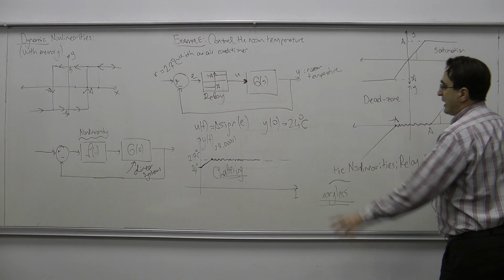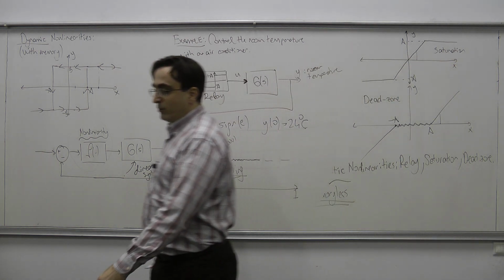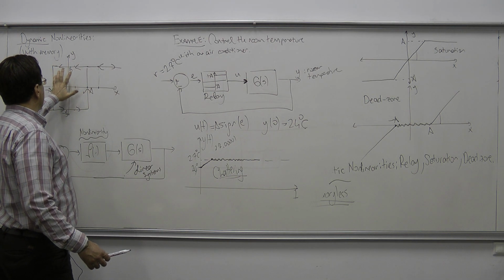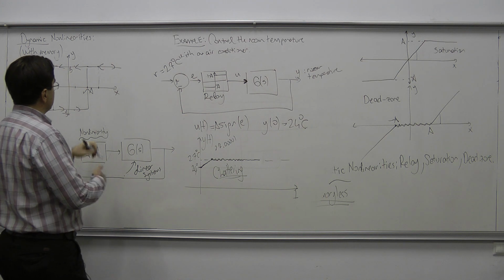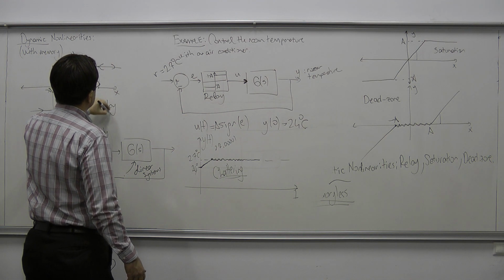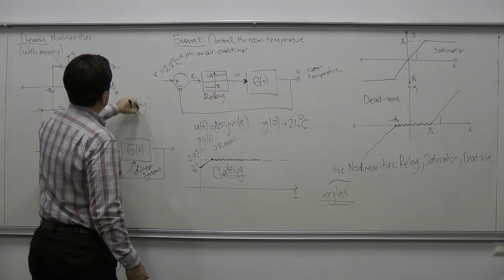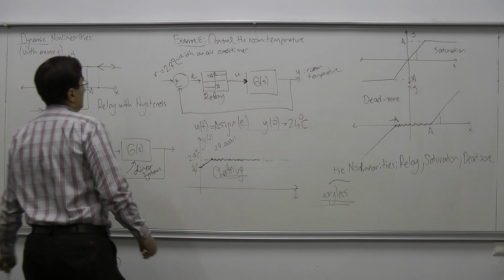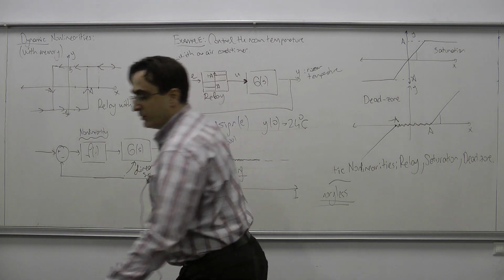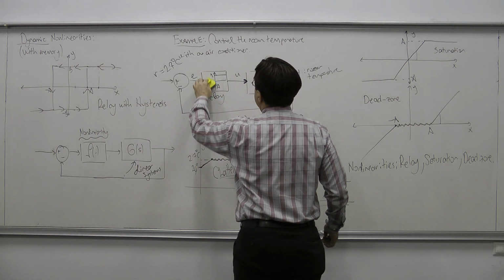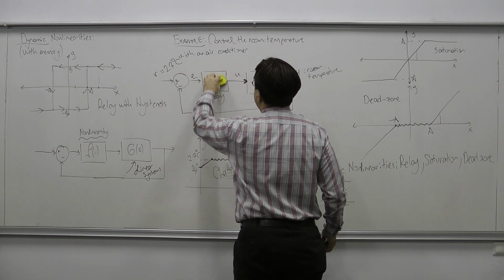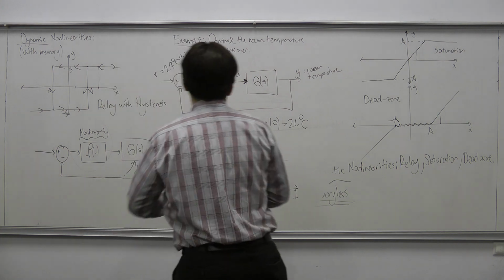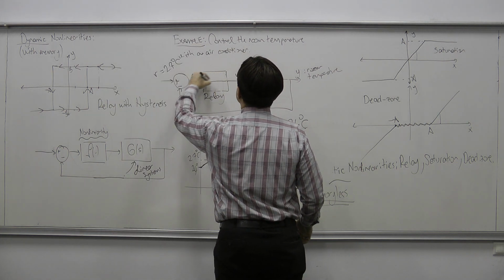It's going to get old quite soon. All right? So that means that we need to avoid that type of chattering, and that is where this type of relays with hysteresis might be useful. Relay with hysteresis. Okay? And what does it do? So let me say that instead of this perfect relay here, let us say that I put here a relay with hysteresis. Okay?